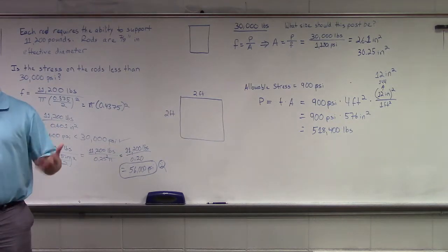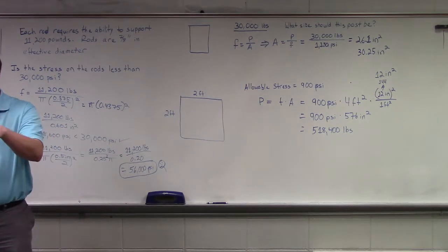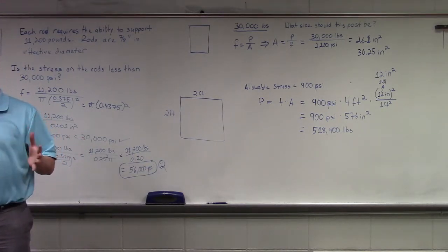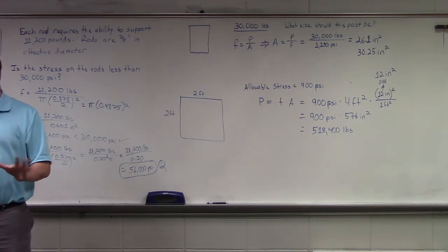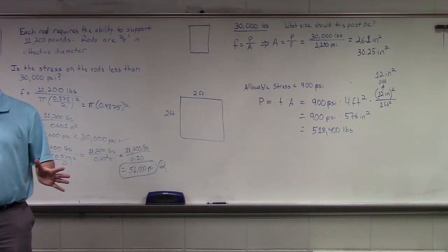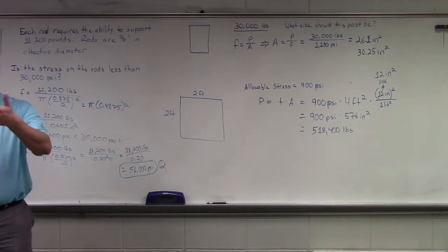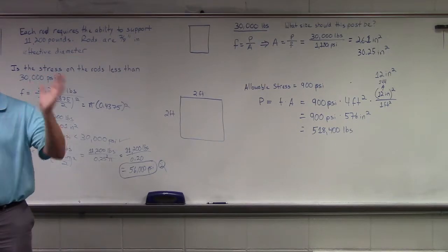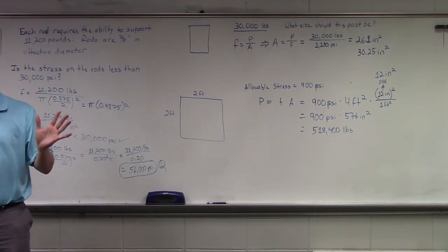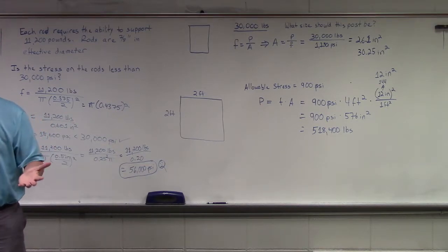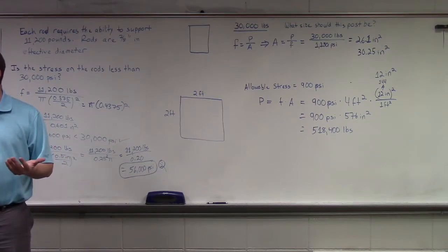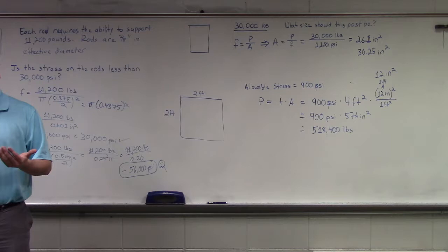Yeah. Essentially, chapter 2 talks about factor of safety. From a building code standpoint, you're not supposed to use factor of safety anymore, but what actually happens is factor of safety gets used all the time. They'll assume the average American weighs 150 pounds, I don't know what the actual number is, and your occupancy is going to be 300 people. 300 people times 150, and then you'll typically multiply it by a factor of safety for live loads; structural engineers are usually using 2.5 or 3 currently.